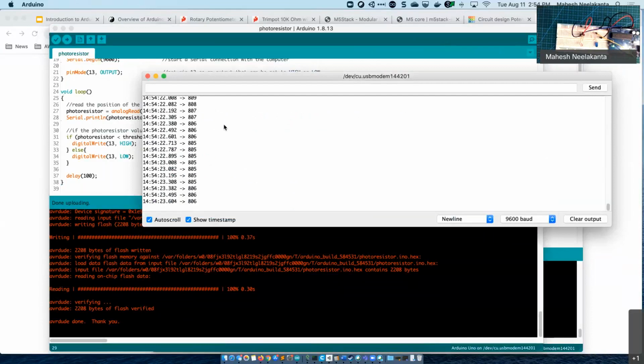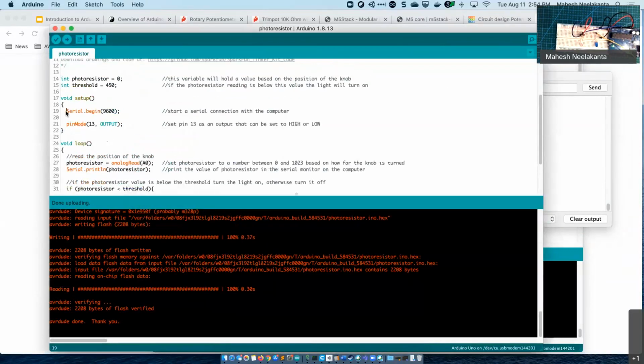And I think last time I mentioned, make sure your baud rate matches. For example, in this one, it says 9600 baud. That matches the serial.begin right there, that it says 9600.